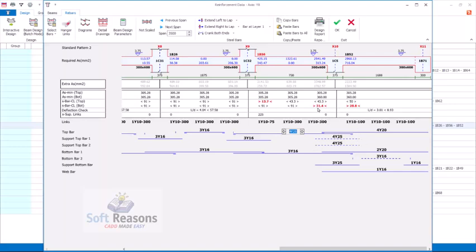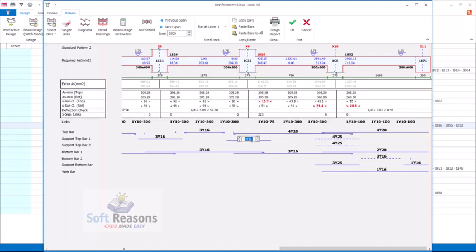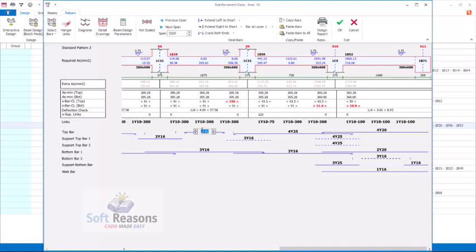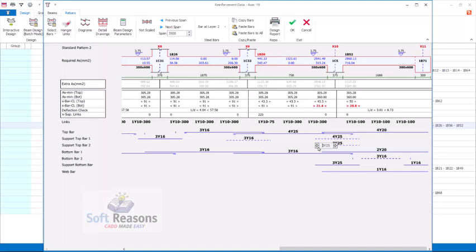Then for here we are having this, you need to make it second layer bar, and then this one you need to lap it as well to correct this space issue. You can see it there. So over here we are still having some space issues, so we can reduce this reinforcement. As you are reducing, be checking the area of reinforcement up here, because it will affect it. You can reduce this diameter of reinforcement, increase it.